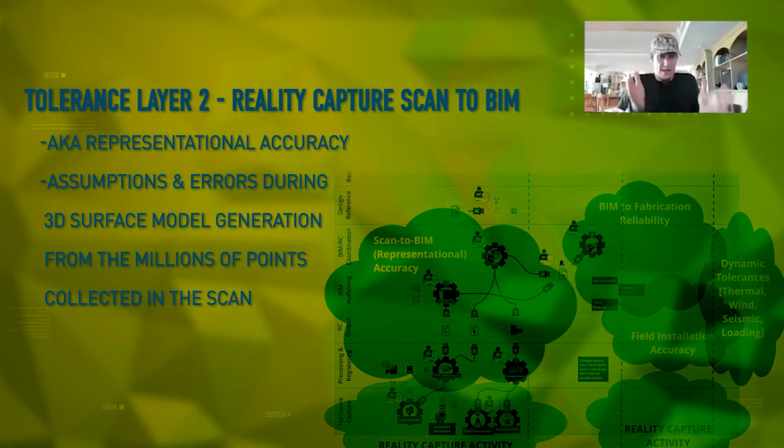Since every single measurement has a plus or minus precision issue, if you chain 100 measurements together, your potential error is plus or minus 100 times that individual measurement. Now, it never works out that bad. It's never 100 times worse, but it can be a lot worse, and it just depends on how it turns out.